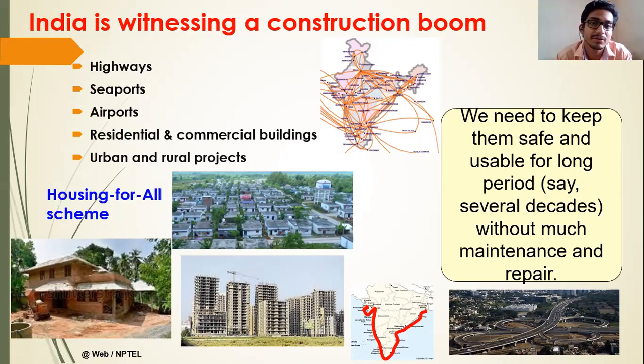You cannot find an intact concrete structure throughout the lifespan of the structure. No matter how good the quality of work is, it's not possible to get concrete without cracks. So it becomes mandatory to repair the concrete structure after a certain time or after certain decades. So we should ensure that the repair work is also good and durable.